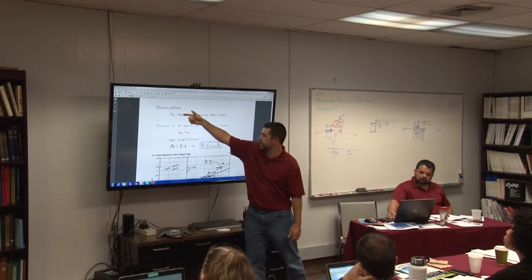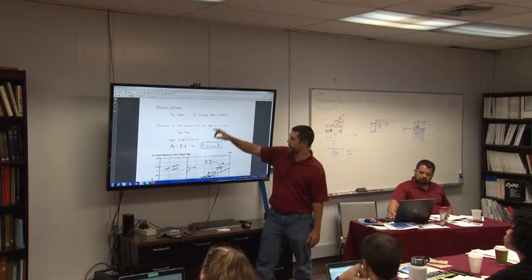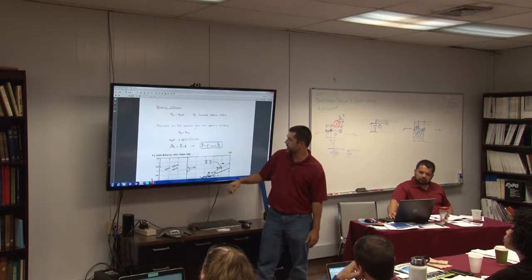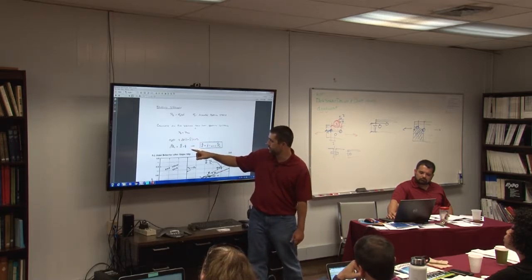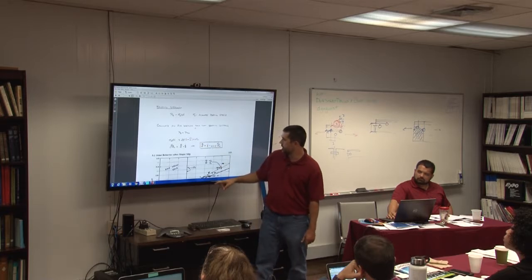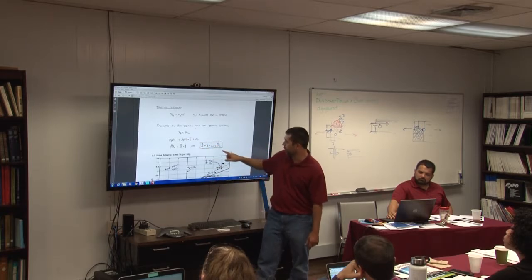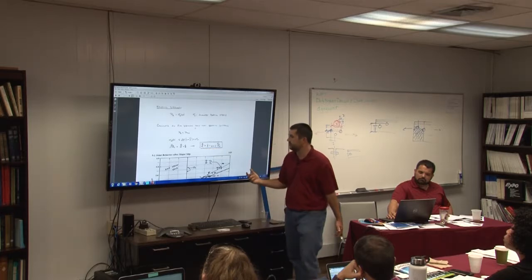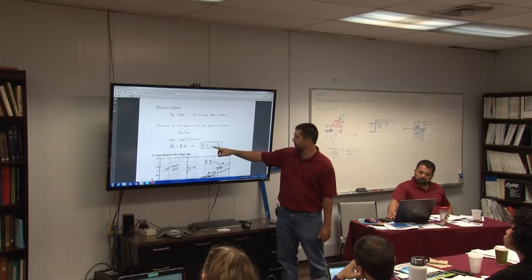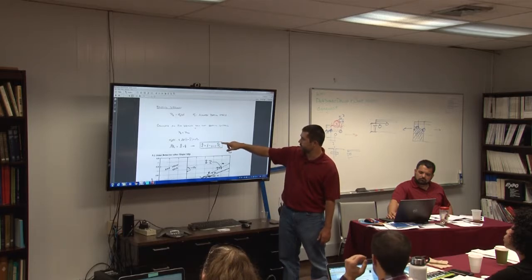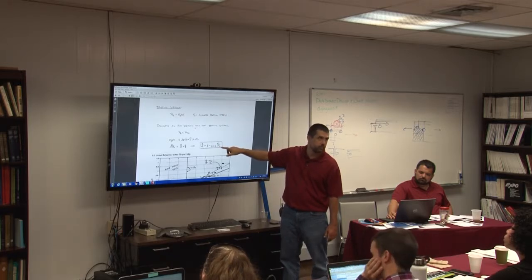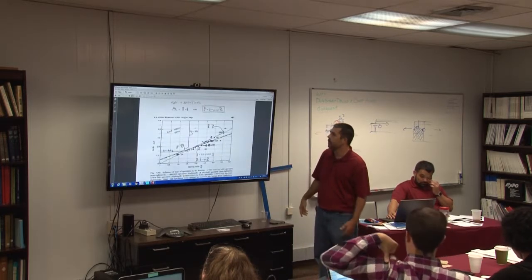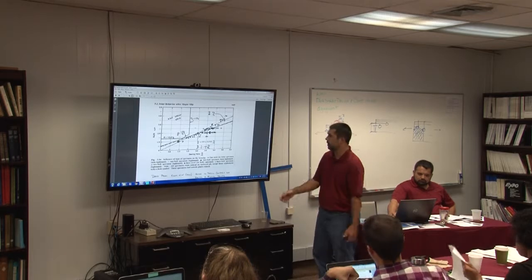So if I take this equation here and set it equal to the equation from above, I can reformulate these two equations, and I get this relationship for end distance divided by diameter. End distance divided by diameter is 1/2 plus 0.715 times the bearing strength divided by the rupture strength of the material. Okay, I get this relationship. Scroll down. Why that's important.